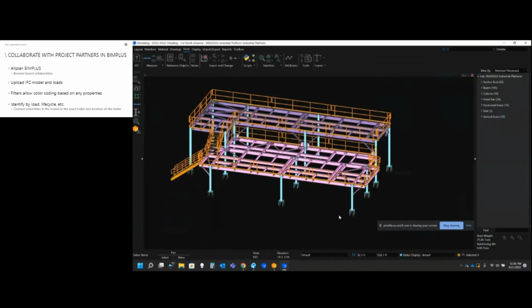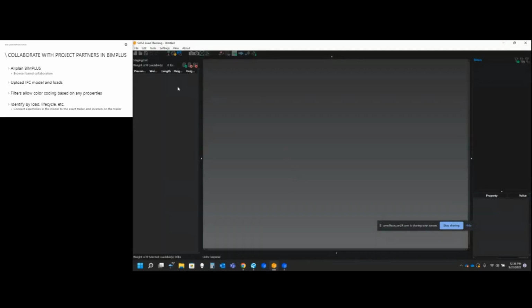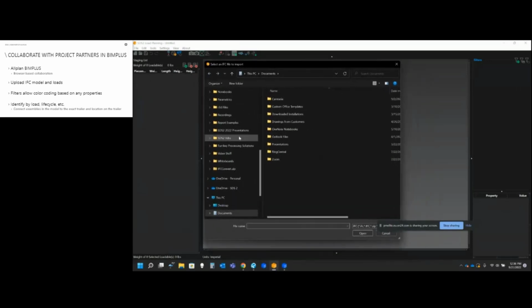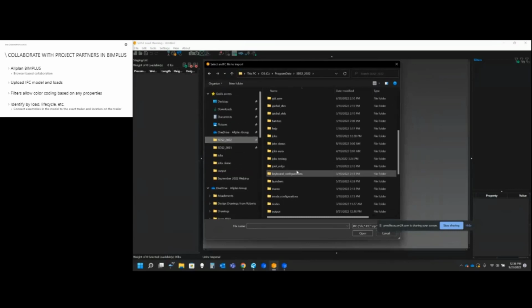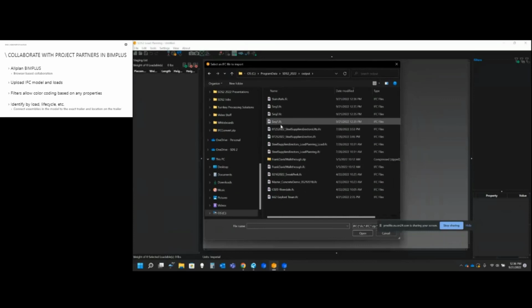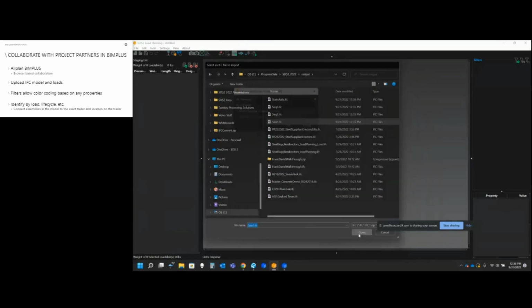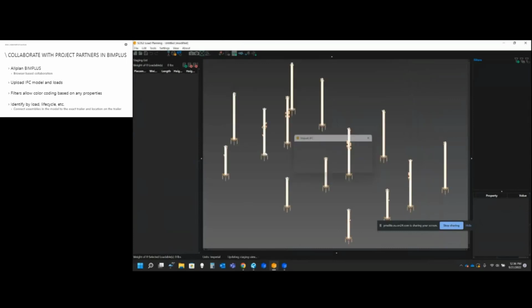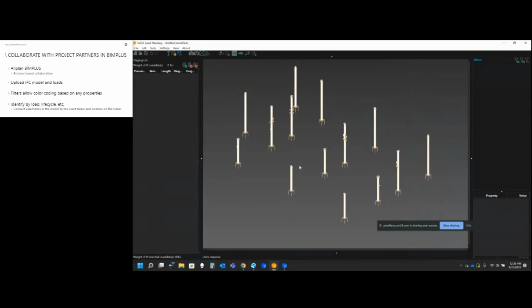Okay, so I've got 4 different IFC files now, right? So back in load planning, let's start bringing these in. I can go ahead and do a file, import IFC, import the IFC file name, and if I can find where those went, they should have gone here into my 2022 output, and there we go. We got sequence 1. Okay, I can give it a model name. I'm just going to stick with sequence 1. So there we go. We have just those items in sequence 1.